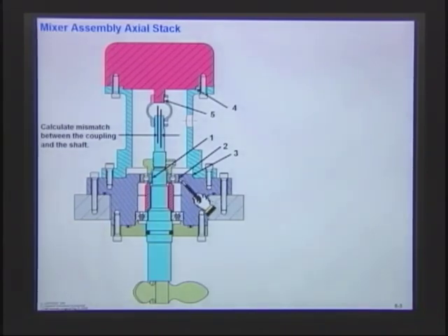Now, if it was a press fit, it probably wouldn't have any impact on us. I guess I shouldn't say that. It depends on what the position callout was and some other factors. But here I'd have another joint, where the bearing fits inside of the housing. And what I did is I labeled that joint number 2.